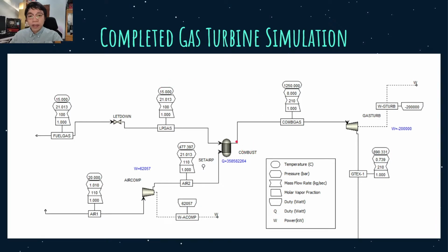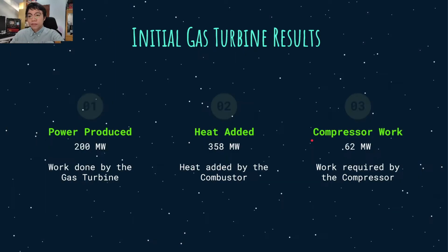And by analyzing this, or even by seeing this slide, we can see that our air that is exiting our gas turbine is at 890 degrees Celsius. Now, this 890 degrees Celsius still packs a ton of heat. And by using this combined gas cycle, we're going to get as much heat from that exhaust gas and transfer it to the steam turbine.